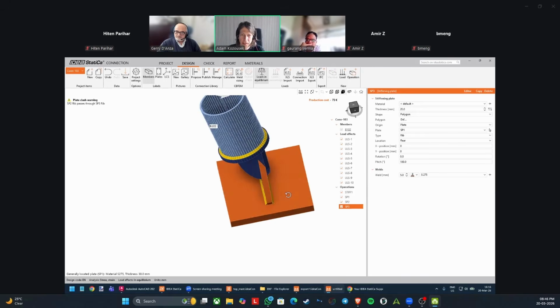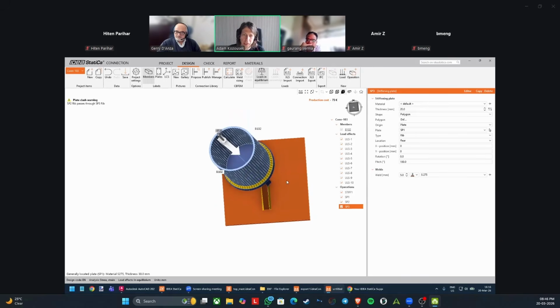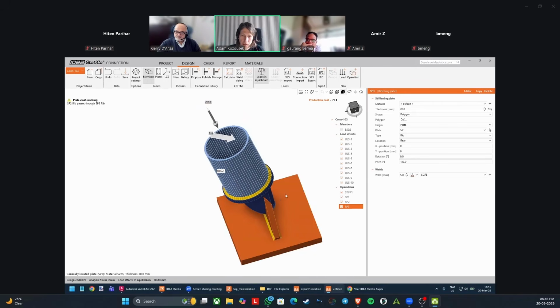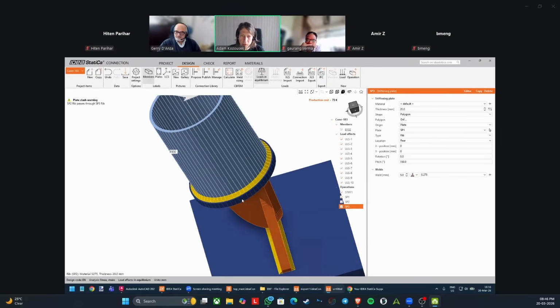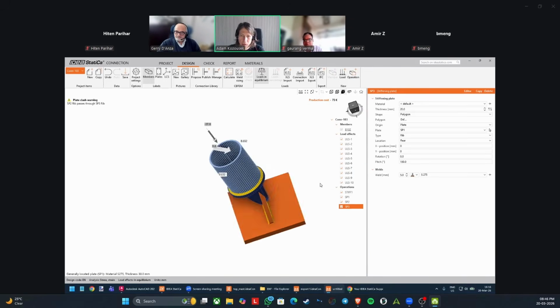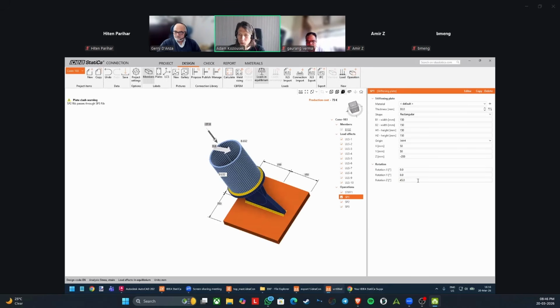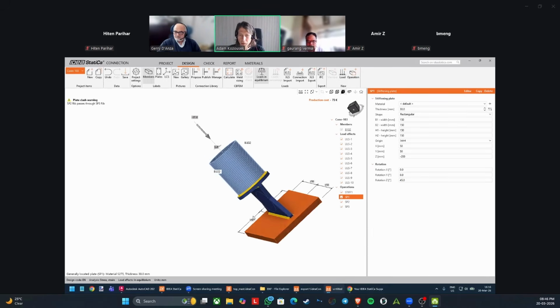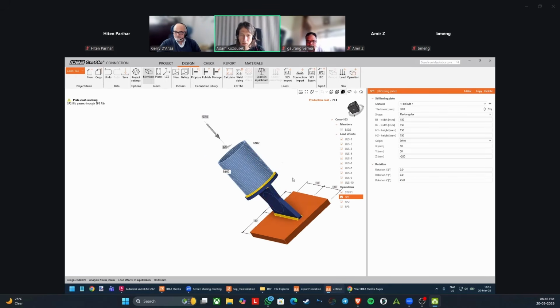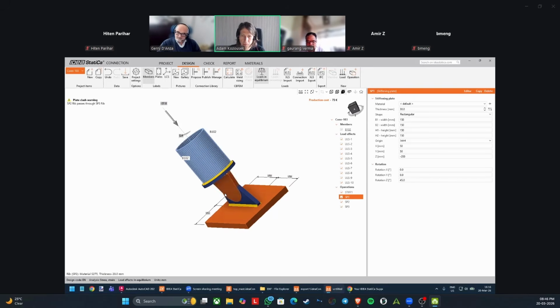How to deal with that? I also want to rotate the base plate to align with this cup plate here. So I go back to the base plate and add the rotation around the z-axis, which is the perpendicular one. I will go to these 45 degrees, which is the angle of the mast.